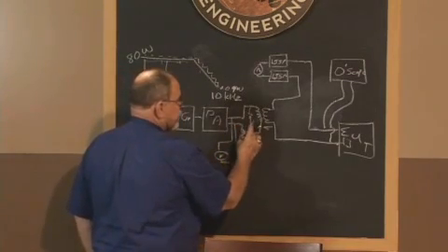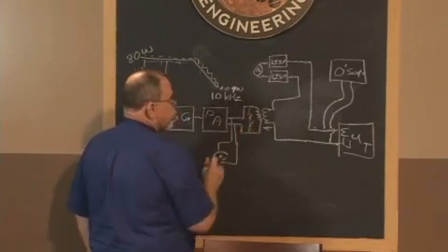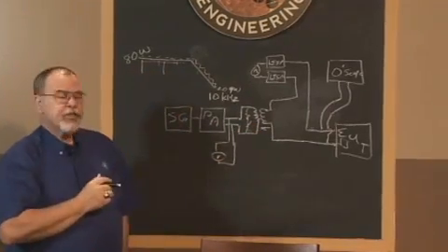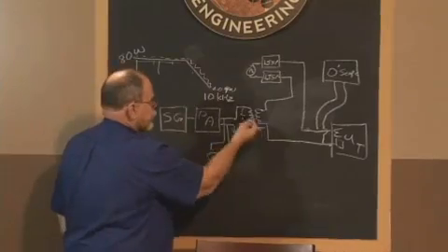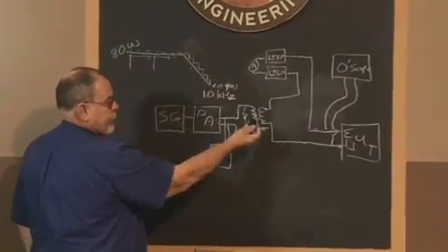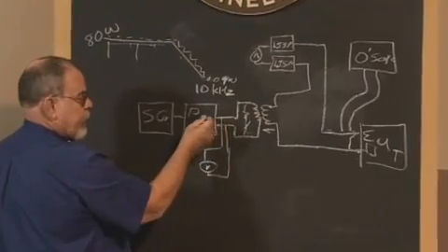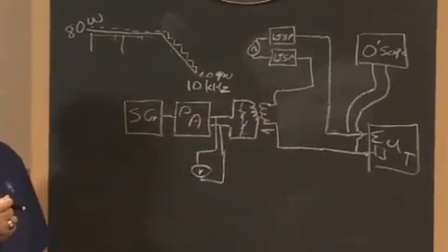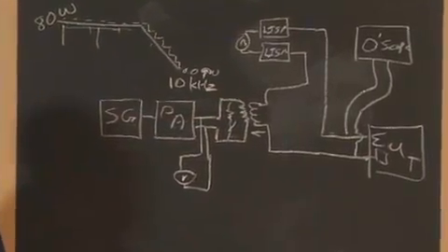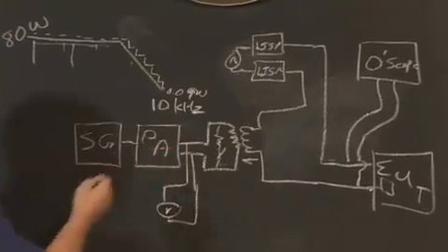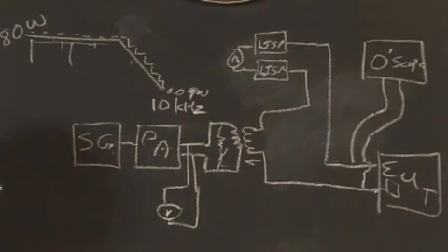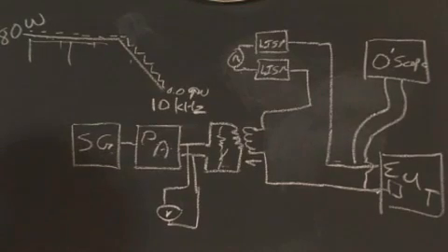So you definitely want to get something you can switch in and out. So we have a process of getting this to happen. Also, we have to worry about the power amplifier. When we feed back this power, it creates a voltage across the power amplifier, and the amplifier may think there's damage tolerance, that it's overpowered, overcurrent, so it may turn off to protect. So then the circuit becomes open and we don't operate well.